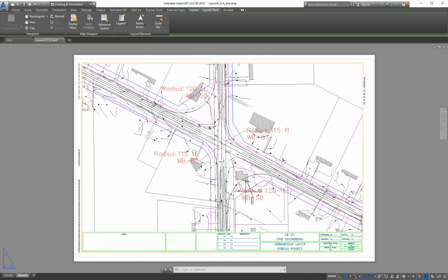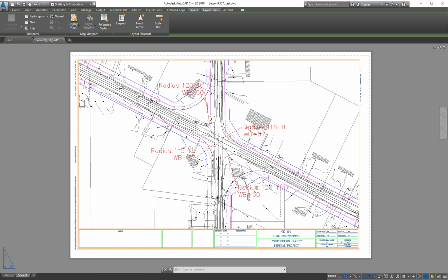And the right answer is: paper space is the sheet, and that's where I put all my dimensions, and all my callouts are on paper space. Right, so that is the proper answer for that. Model space is just all of your design pieces, right? And that's all of the real world design things. Paper space is the actual presentation that we're going to print out and give to the contractor or give to the client when we're done. So, long discussion because this is a super big deal and important, right?